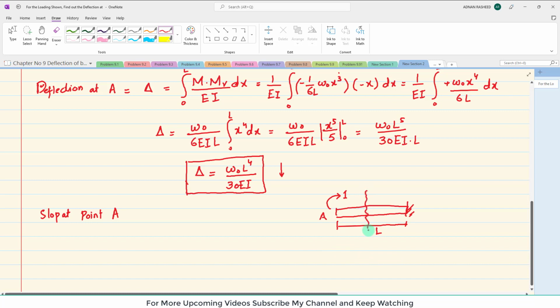So if we cut this section at 1-1, there will be the unit moment that is given, a shear force and a virtual moment reaction, and let this distance be x. We will apply sum of all moments about 1-1 equal to 0, taking counterclockwise as positive.